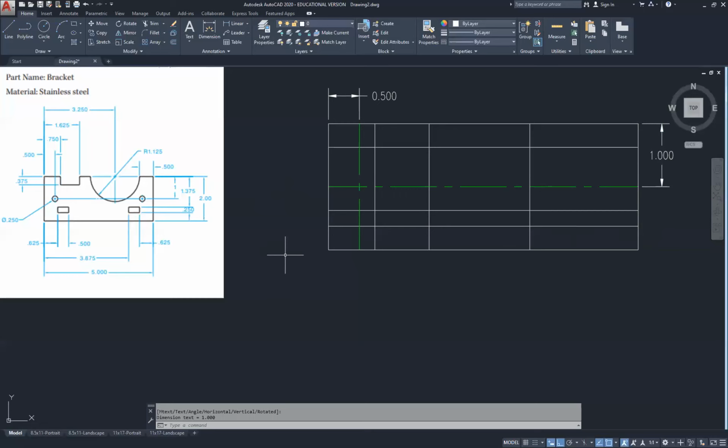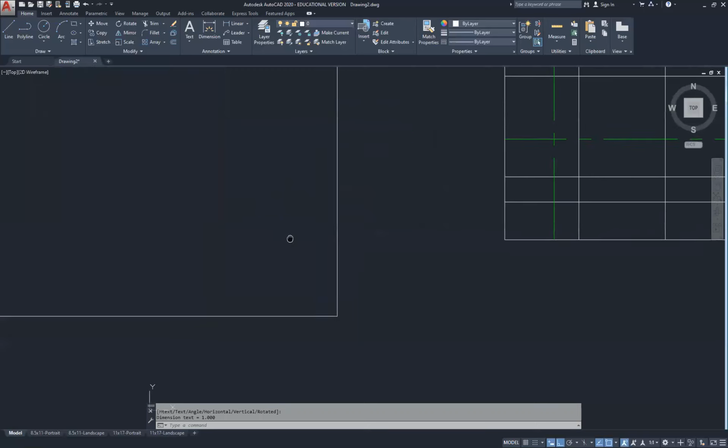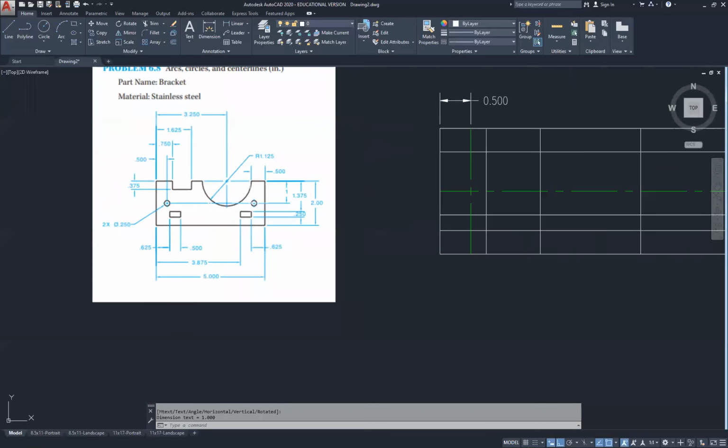Now in this drawing, it's not specified where this hole is located right here. We're going to go ahead and make it uniform with the piece because we have a dimension here of 0.5 with this dimension here, and it's at 2 times with them being in line. So we're going to make that one a 0.5 as well.